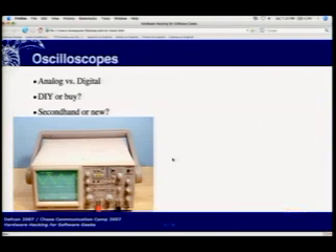Another useful use for an analog oscilloscope is when you're debugging your PCB layouts and you're looking for EMI, which might be affecting the operation. So you don't know why it doesn't work, and you've double checked your logic 15 times. You might find that interference from, say, your power supply part of the board is coming in on your analog inputs, and it's not properly isolated with the grounding, and the components are too close, and you might get some signal leakage even though the traces are isolated, but they're just too close on the board. So that will show you exactly what is on that wire and what is on all the other spots without having to guess.